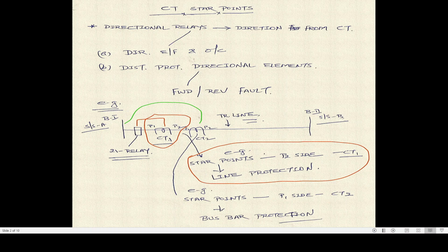In order to understand the transformer protection like the differential protection and REF protection, you must understand the CT star points and CT polarity connection, which we will discuss in the next session probably. In this session, we will keep ourselves only up to transmission line protection.